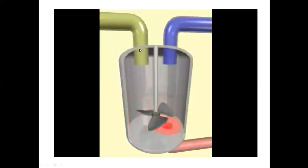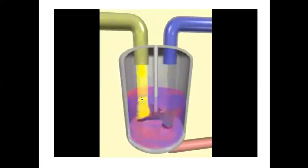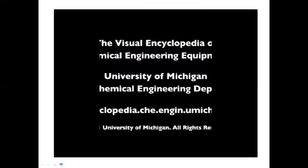So it could be that the first reactant is introduced, followed by the next, but they are allowed to react first here. Then that's the time that they are withdrawn. Unlike the CSTR, wherein you have continuous addition of reacting species and continuous removal of the product. In the case of the batch, it is not like you put the first reactant in the tank, then the second reactant, then allow them to react. No, they are put into your reactor together.